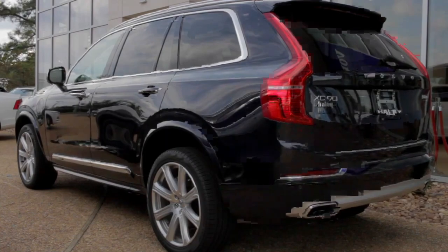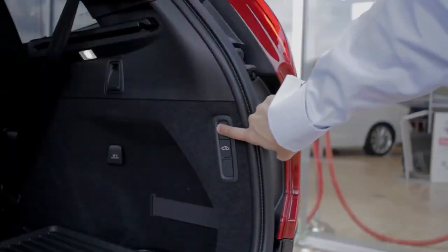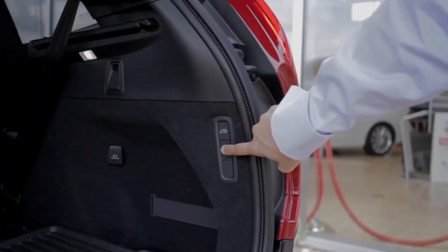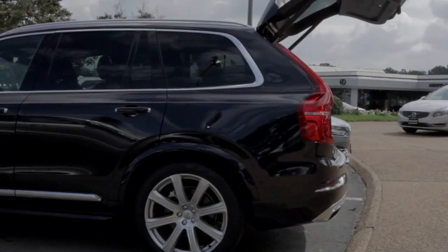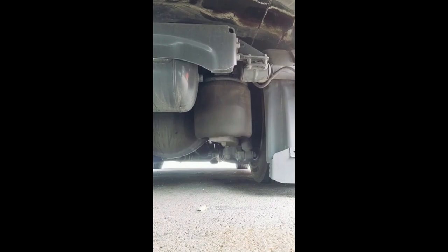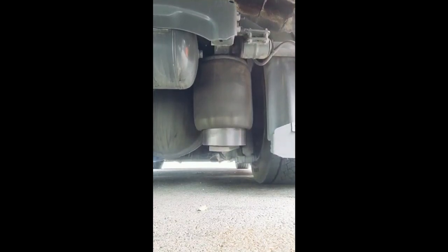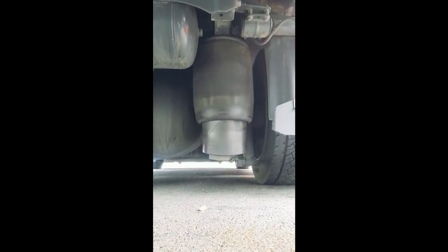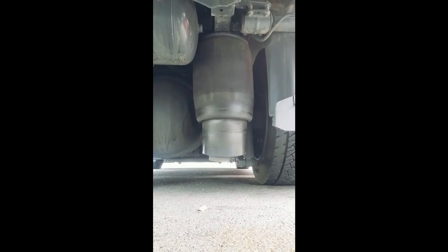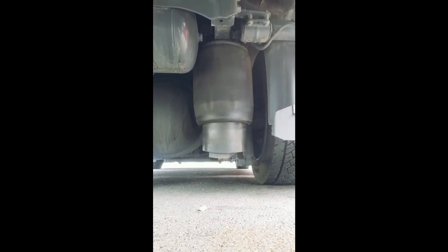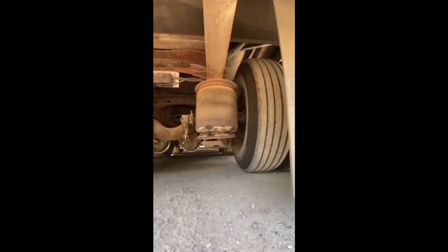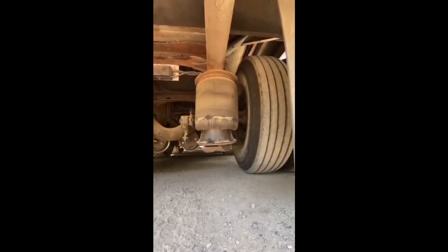The HCV linkage then returns to a neutral position, and the valves likewise revert to their initial state, securing the airbags to maintain the appropriate ride height. Conversely, when weight is removed from the vehicle or the suspension system, causing the load on the axle to shift back to its original position, air is released from the airbags via an exhaust port. The HCV linkage returns to its neutral position, and the exhaust port is sealed, trapping the remaining air inside the airbags to maintain the correct ride height.